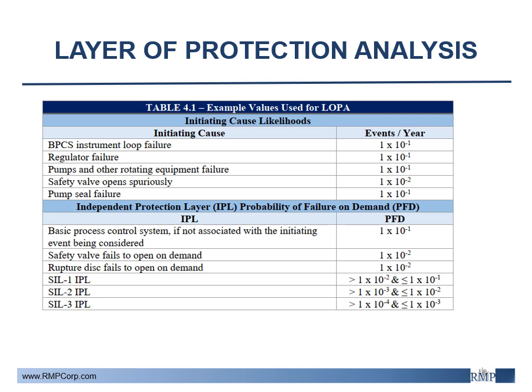And what we're going to do for LOPA is multiply these values, and that'll get us our likelihood that the initiating cause will happen and our safeguards will not help us. So this might give us a good idea of whether we want to include more safeguards or, in our case, increase maintenance.